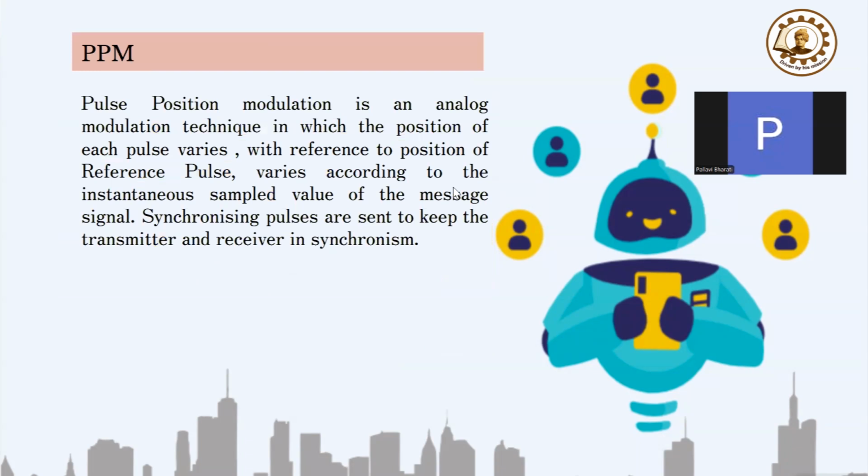Now, finally, we are coming to the PPM, that is the pulse position modulation, an analog modulation technique in which the position of each pulse varies with reference to the position of the reference pulse, according to the instantaneous sampled value of the message signal.